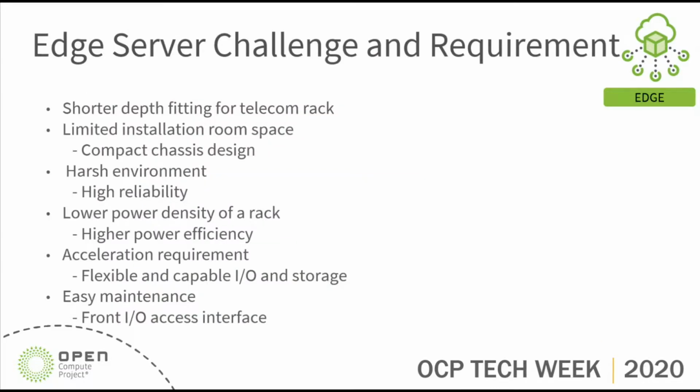Okay, let's go to topic one, the edge server challenges and requirements. As we know, the server market is going to deploy from the data center side to the edge side. But on the edge side, there are some challenges for the deployment. The first challenge is that the server design should be short depth. The purpose is to fit the telecom rack. Generally, the telecom rack will be 600 millimeters in depth.